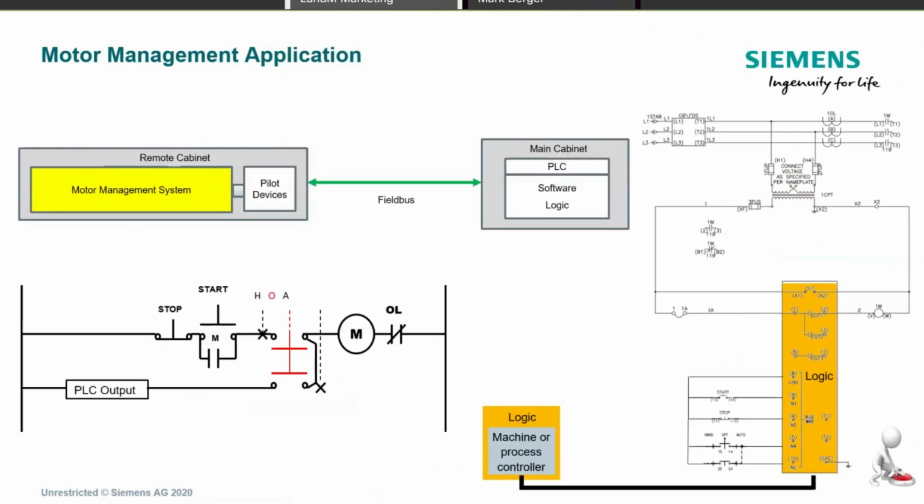Okay, we introduce the Simocode, and note that it removes the extra contactor that is needed for the sealing circuit. And note that it removes also the contactor for the overload, because the Simocode is the overload, so we are removing those. And then in addition, we're removing the CT. We don't need that because the Simocode has a CT, a current transducer, and a voltage transducer if you want to measure voltage, all in one unit.